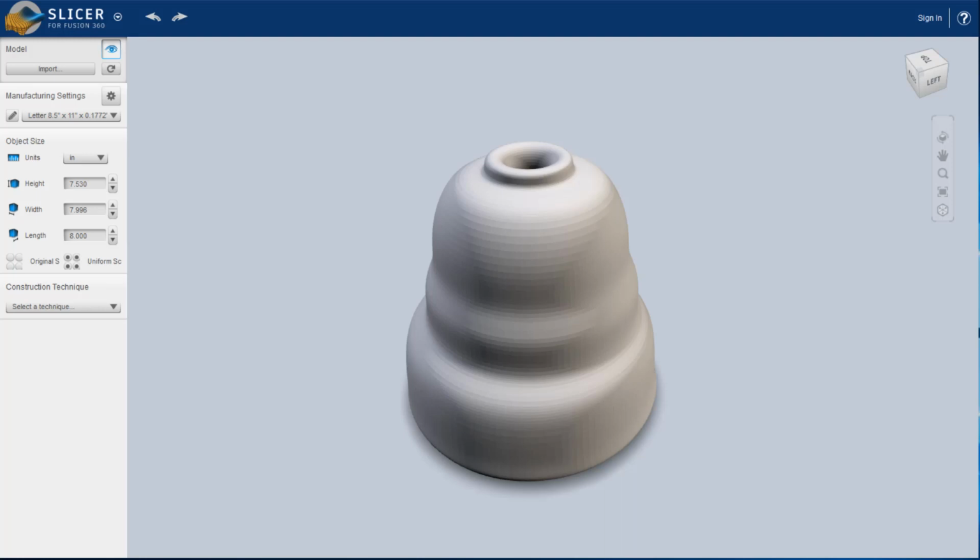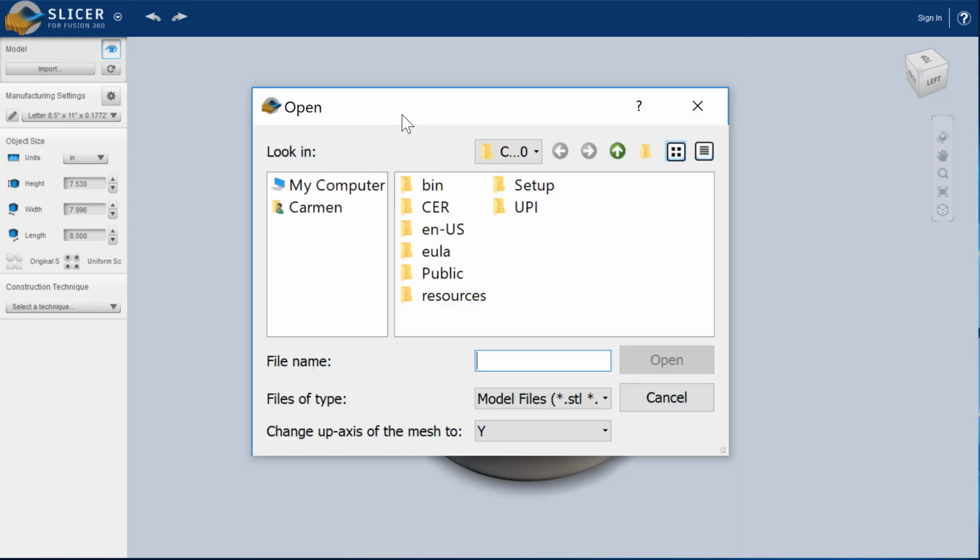This short tutorial will show you how to use Slicer, which is an Autodesk program that helps you convert a digital model into a physical model. You should go ahead and export your Rhino file as either a .stl or a .obj. I would try both settings and see what gives you the best result in Slicer.